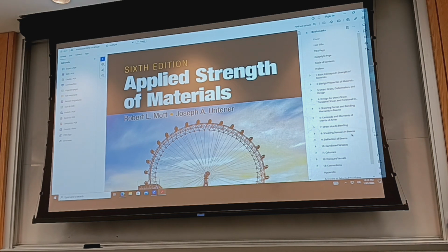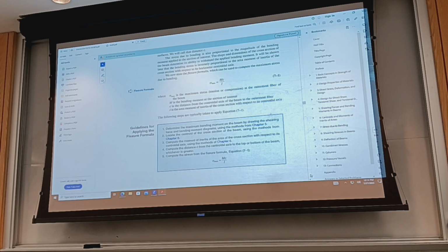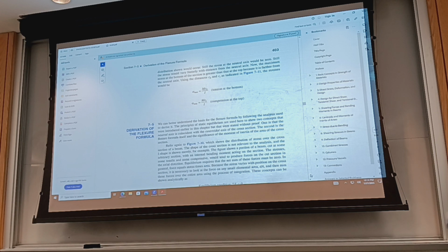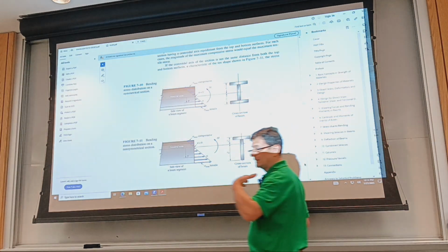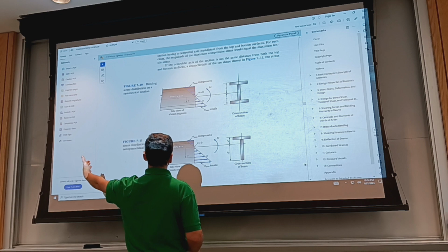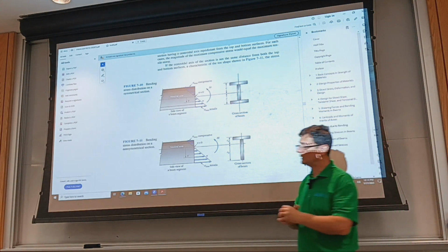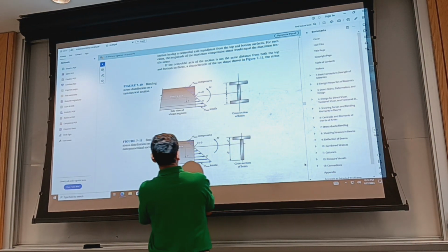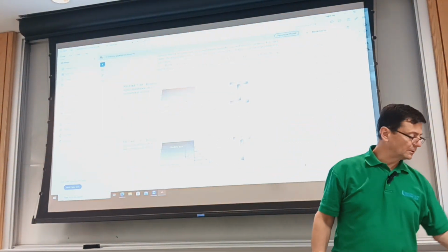Shearing stress in beams. So we covered the section stress due to bending. Now, going to where it shows the stress distribution figure like this one, this is for the left-hand side. We move along, starting from the far left end of the beam, the x-axis coinciding with the centroid, and the stress distribution is as you see it here, and these are tensile and compressive stresses.